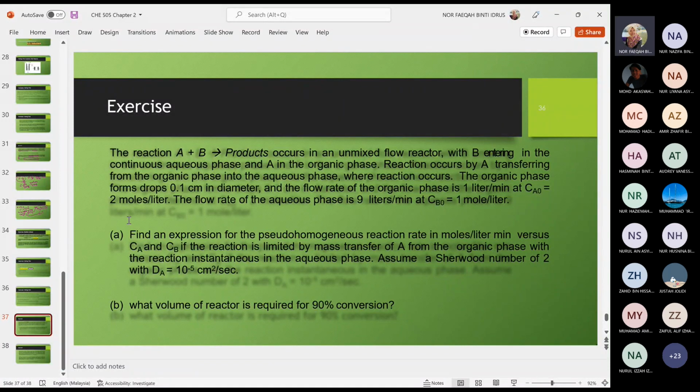It doesn't tell us the type of reactor. If it were a falling film, it would tell us, because a falling film is easy to recognise, it forms a film. That is a falling film reactor. But this type of reactor is usually a bubble column or a spray tower, but it doesn't state it in the question. But usually how do we predict whether the reactor can be modeled as a PFR or as a CSTR? Based on the conditions of the reaction.